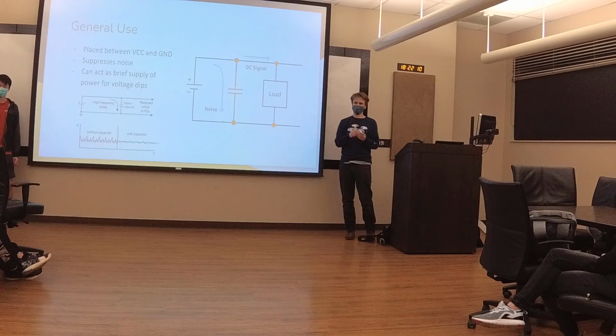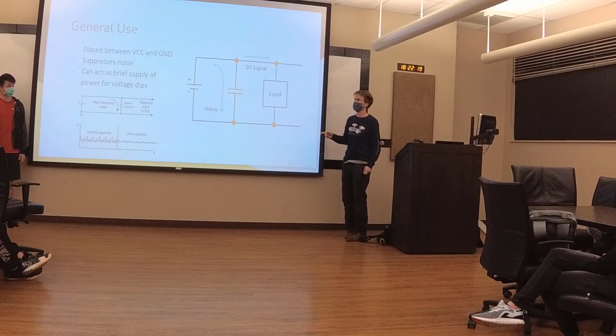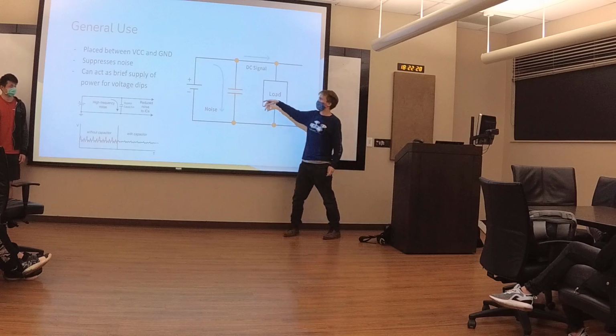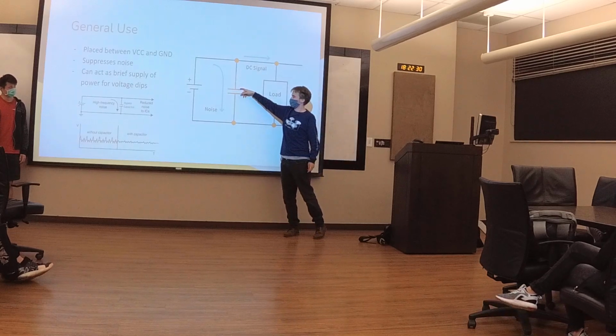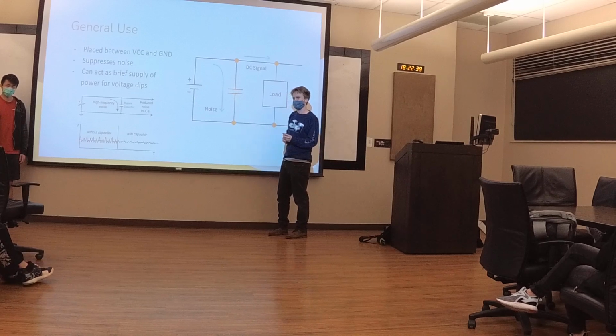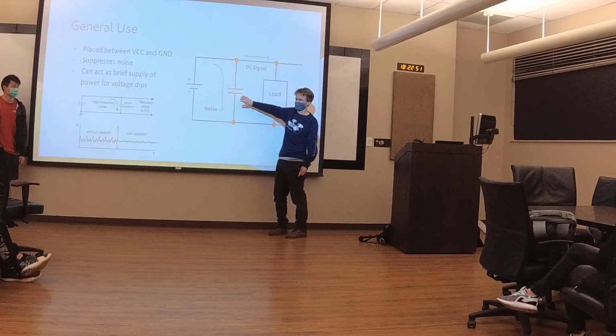Yes. So are we going to add a resistor, or are we going to short basically across the capacitor? No, we're not. The impedance is an intrinsic part of the capacitor. The impedance of a capacitor is 1 over j omega c. I think your question is like, how does current get from here to here, essentially? It won't short because this isn't open, right? These two plates are not connected in any way. So you don't need to worry about there being a resistance.